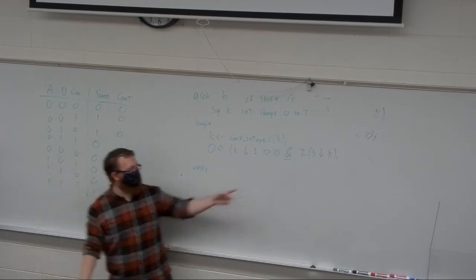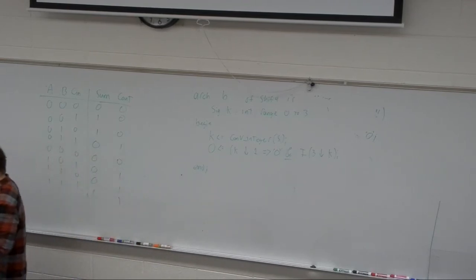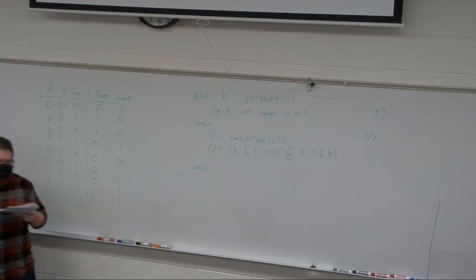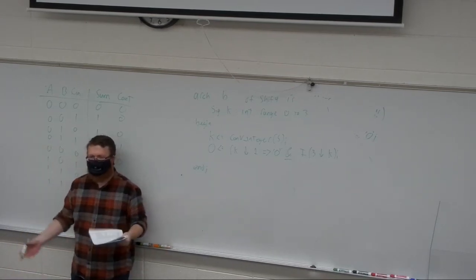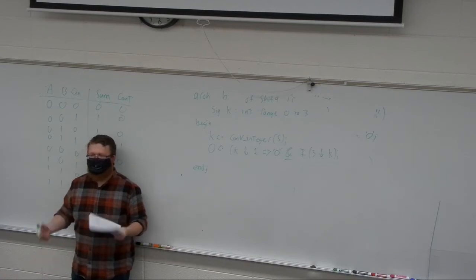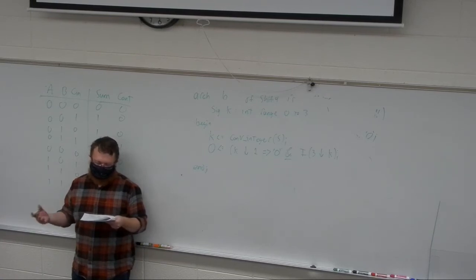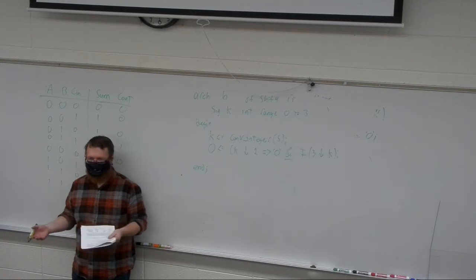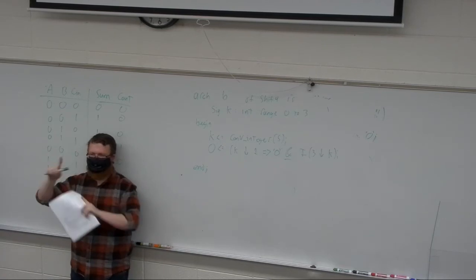That's a shifter. A zero fill shifter, specifically. We could also make it like a one fill shifter doing various other things. They do in the book on figure 11-18 show you various types of shifters and their implementations. I do suggest looking at them. So they have like a shift right with sign extension. They have shift left with backfill. They have shift right end around and shift left end around. So shift left means it shifts left and wraps around. Shift right is right and end around, right?